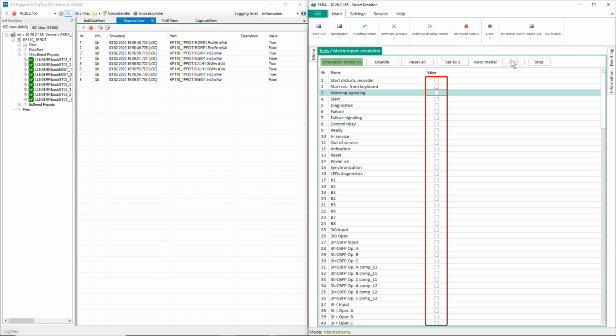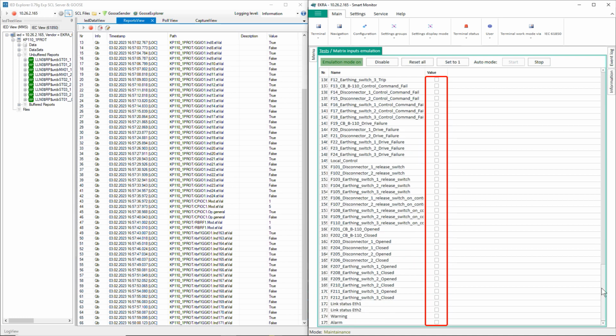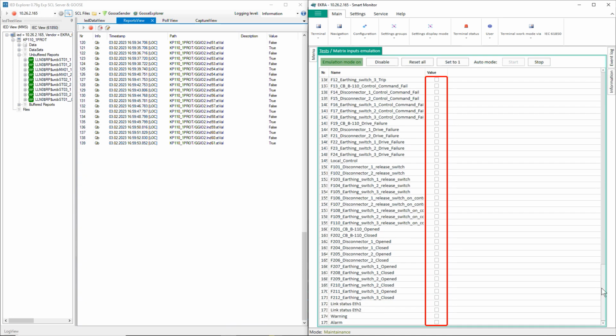Every signal is set to logical 1 for 1 second, then reset. A pause for 1 second is kept before moving to the next signal. Test is deemed to be completed if it went through the sequence of all listed signals.